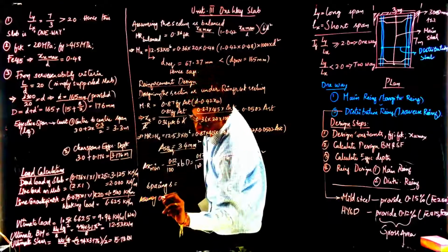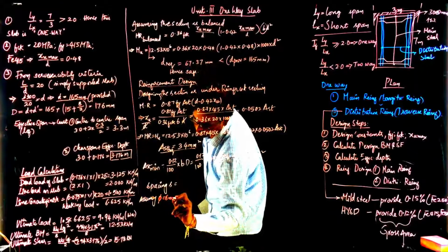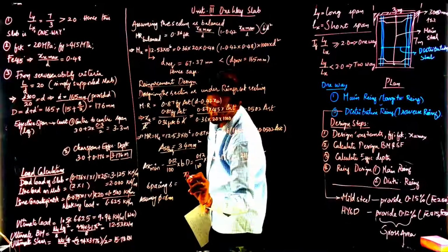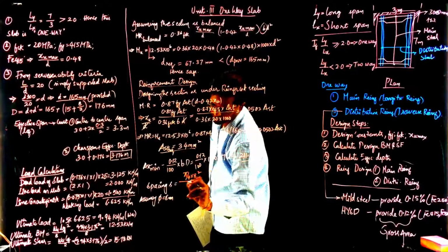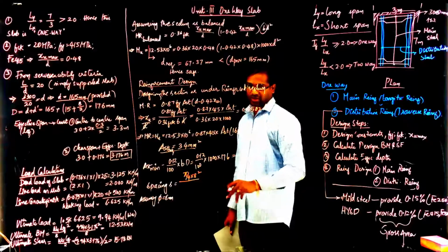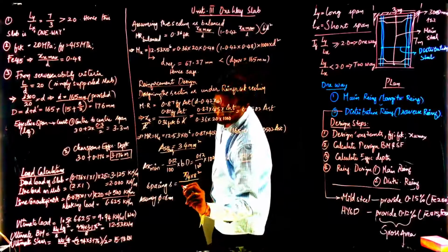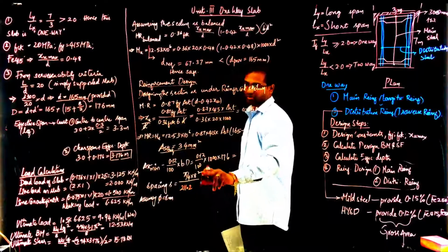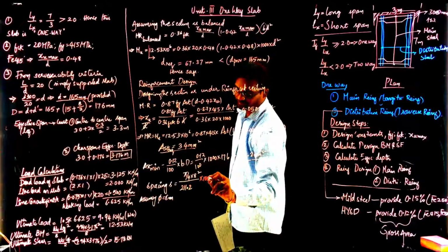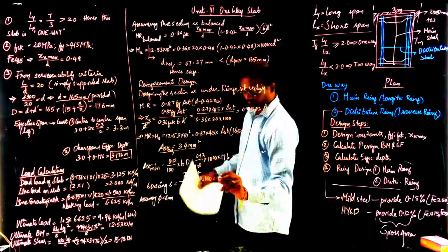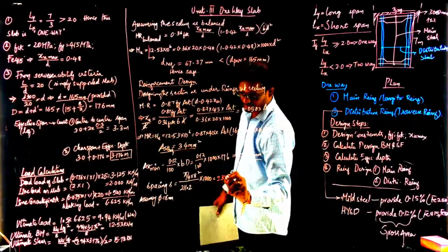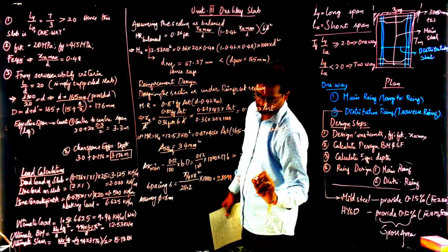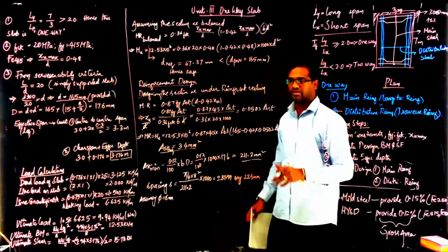In the numerator you put the area of the provided diameter, and below you put the required area, and multiply by 1000. Then you will get the spacing. You have got 237.99, so I am taking this as 225 mm. Always keep these values in multiples of 25.